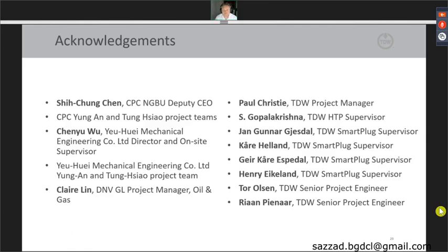Thank you, Gary. One question was posed by Mr. Vignesh PV. He is referring to online isolation, whether all the valve replacement will require hot tapping, that is, the online isolation stopper method. I'm not sure if I understood that question correctly, but you could use hot tap and stopper as an isolation method in the same way you used smart plug, if that was the question from the gentleman.